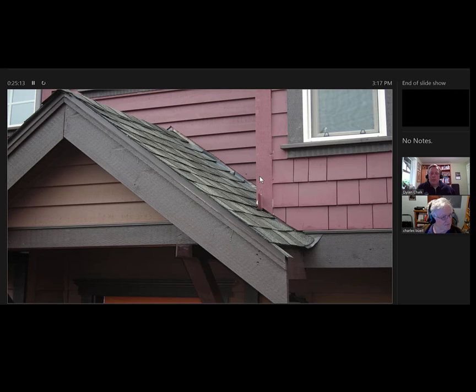I think so. But another place you can have redirect flashings would be places where the roof doesn't drain properly. What we're looking at is a picture of a small little gable roof above an entry, and it's draining toward the side of the house, which is always a super counterintuitive design. Typically, they'll install some sort of really low, usually single ply membrane covered triangular valley there. In the old ones, they'd be like a torch down or something. Sometimes that's all you can do, but the torch down ones on a 50-year roof.